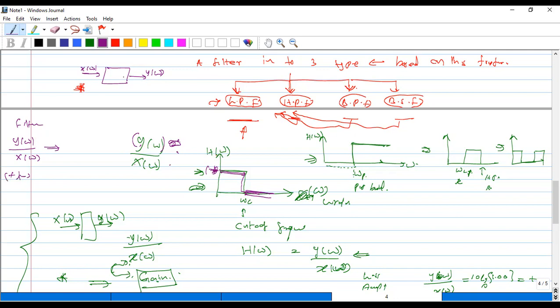This is a passive device. There is no multiplication, but there can be loss. Yes, it should be minus. Very good. It should be minus because this filter is a passive device. There is no multiplication, but loss can be there: connection loss. Also, these passive filters are normally LC networks, and resistors are also there due to the line, so the losses can be there.